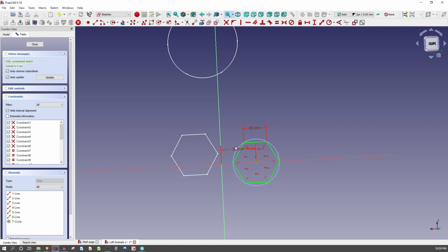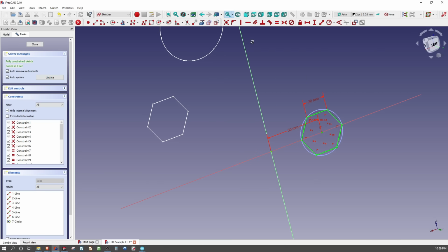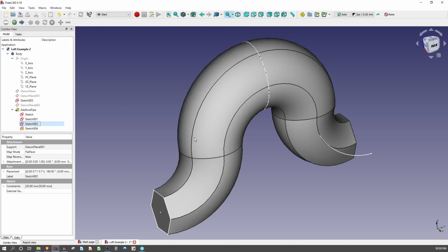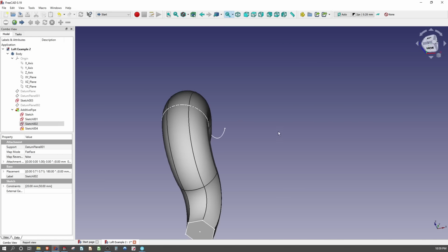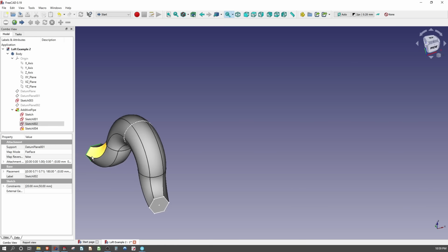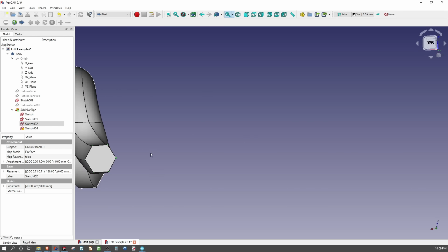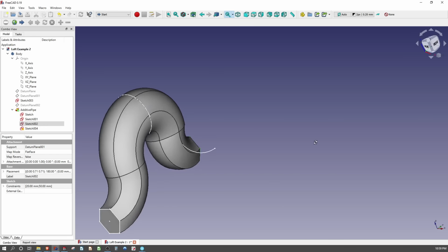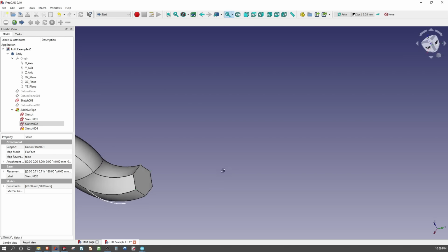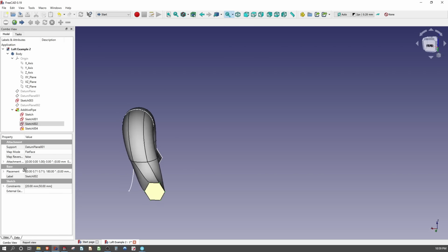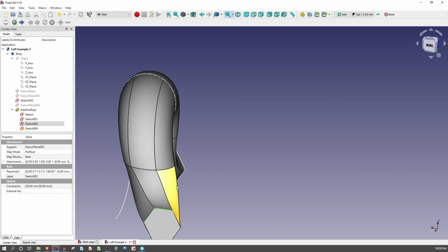And let's say I move this 30, maybe 50 millimeters away from where it was. Well, now I'm off plane from my path. So let's close that. And as we move transitions, you can start to see that our end features might not come together the way that we want to because we twist at the end.